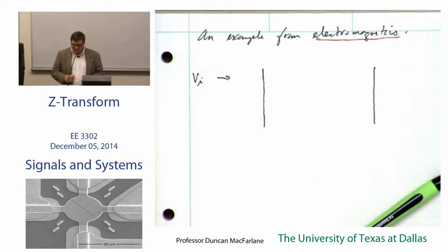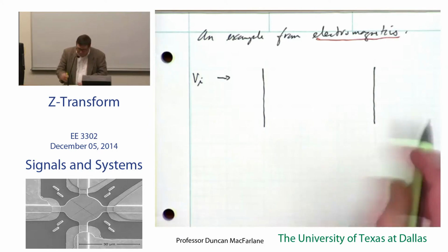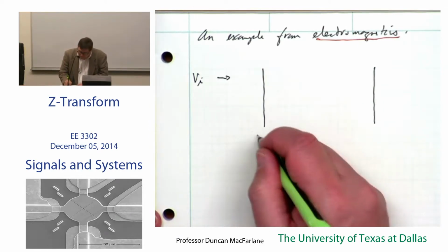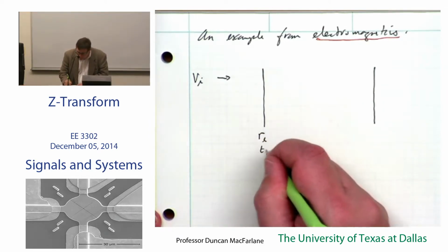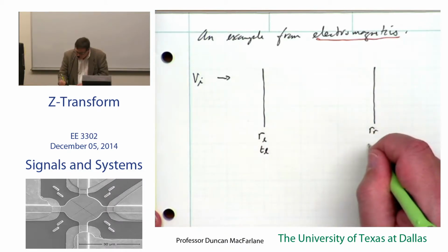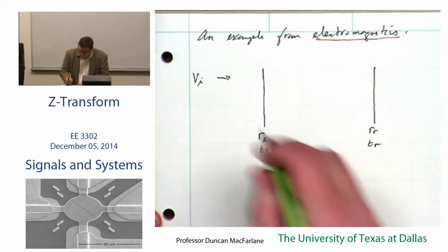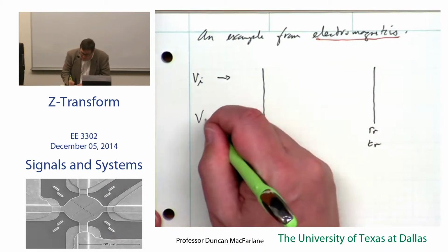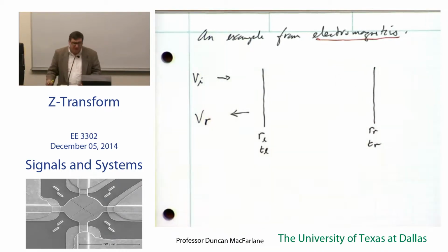don't have that impedance. And what will happen is if you don't match your impedances at either end of your transmission line, you'll get a reflected wave right back at you.